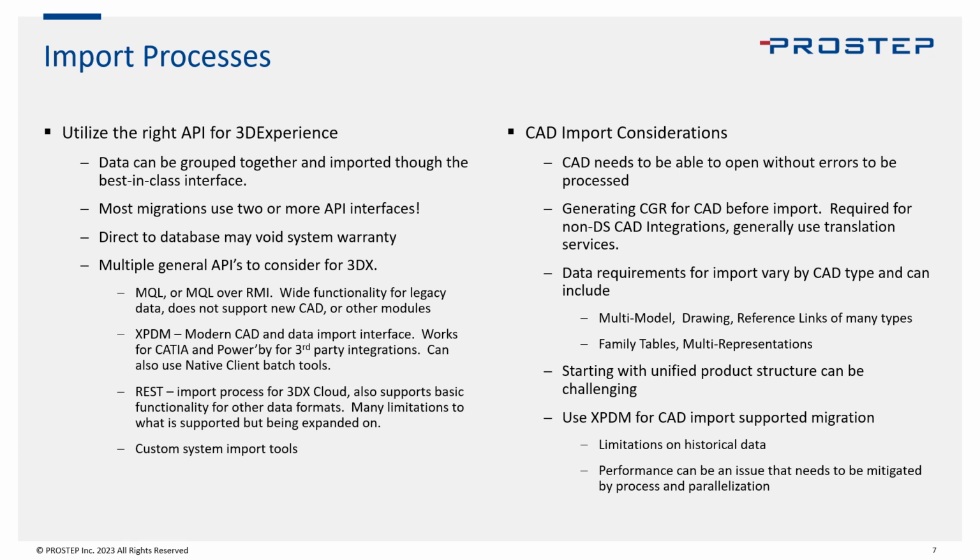And just a special note about the unified product structure, UPS. When you're dealing with the UPS, sometimes you really need to work on merging data that might be available or having different representations of data created within 3DX. Many source systems might have a design and an engineering BOM, like it's a native concept in Windchill and in other systems. But in the UPS model, those things need to fit together, or you need to specify configurations in order to make sure that data aligns well, so that it's similar when you're pushing that data downstream.